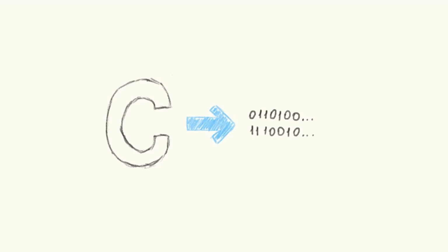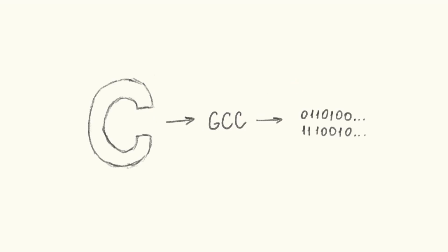How do we do that? In Arduino IDE, it is already done for us. That's why I want to use it. But essentially, how it is done is using a special translator program, which is called AVR GCC. GCC, the GNU C compiler, is a special program, a translator or compiler, that will translate C code to machine code. But what we want to do is to translate C code into AVR machine code, which is a little bit different, but it's still GCC. So we will use the program called AVR GCC.